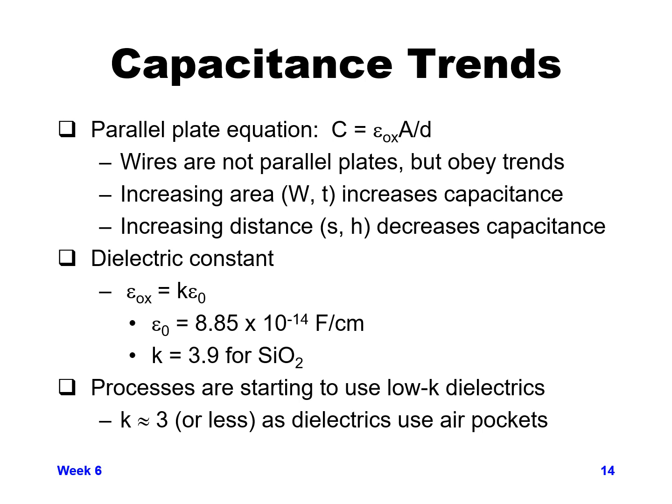But the distance of the wire to the left or right of it is the space. So if you increase the distance to the wire to the left or right, if you increase your space, you can decrease your capacitance. And if you choose a higher level metal that has a larger distance, or more oxide thickness between, so when you get to the higher level metals, the one metal layer to the next metal layer will have a larger oxide thickness between metal layers, which is the H value.